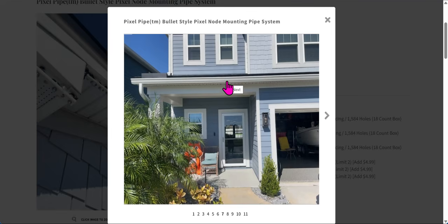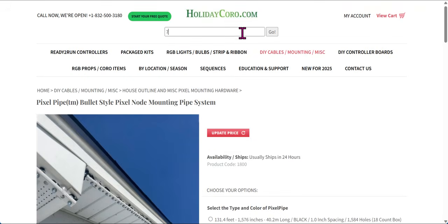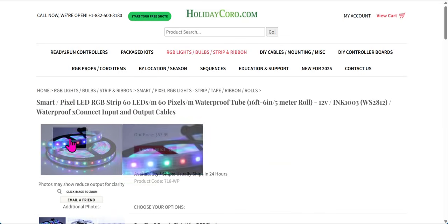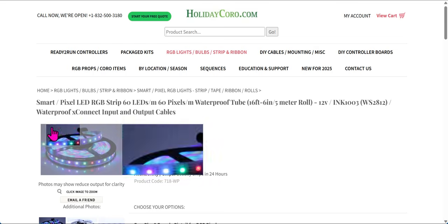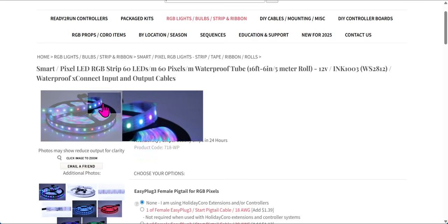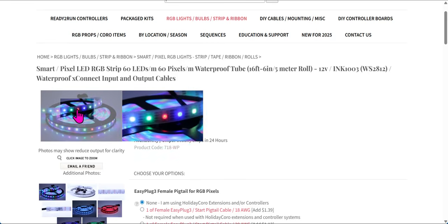You don't want to get super close pixels. This is very common in pixel strips. For example, in products like 60/60 strip, these pixels are spaced at 3/4 of an inch apart. Now here they look nice and fine, they're all individually visible, but when you take and put those pixels onto a house and view them at 50 or 75 feet, these pixels will sometimes color mix.